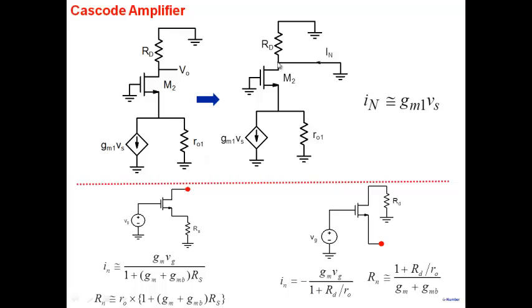Next thing is, let's find out the Norton's resistance here at this node. Now, Norton's resistance, if you look at it, so forget about the ground now. There's no ground. So I'm asking what is the net resistance at this particular node. That will be equal to resistance looking up, which is RD, that's the first term, and resistance looking down.